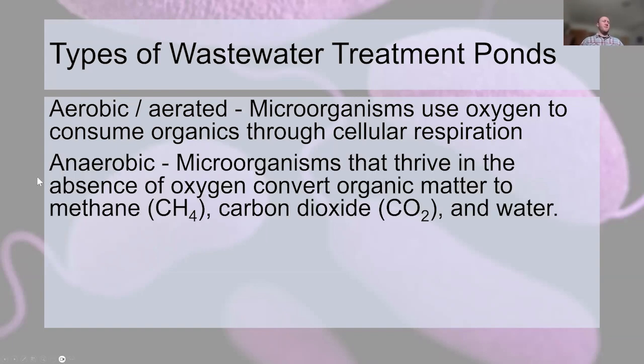And the opposite is anaerobic. That's when microorganisms thrive in situations that lack oxygen. They have different metabolic functions. They convert that organic matter, that carbon, into methane and carbon dioxide. So they have different pathways to treat that wastewater.